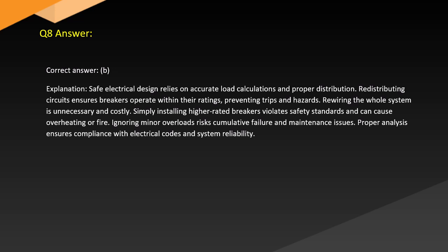Answer. Correct answer. B. Explanation. Safe electrical design relies on accurate load calculations and proper distribution. Redistributing circuits ensures breakers operate within their ratings, preventing trips and hazards. Rewiring the whole system is unnecessary and costly. Simply installing higher-rated breakers violates safety standards and can cause overheating or fire. Ignoring minor overloads risks cumulative failure and maintenance issues. Proper analysis ensures compliance with electrical codes and system reliability.